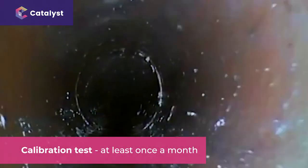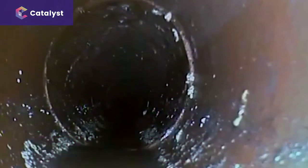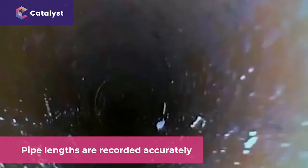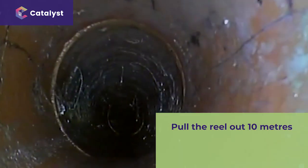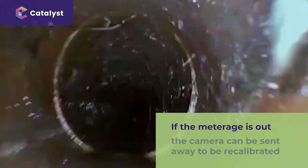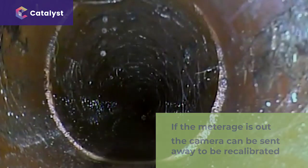A calibration check should be done at least once a month to make sure the camera counter is accurate and that pipe lengths are being recorded accurately as well. This can be done by simply pulling the reel out 10 metres, then measuring it with a tape measure. If the meterage is out, the camera can be sent away to be recalibrated.